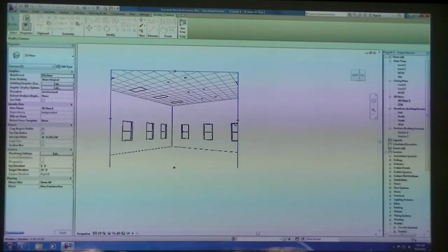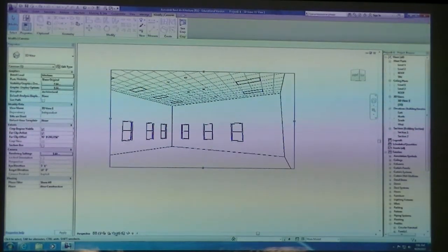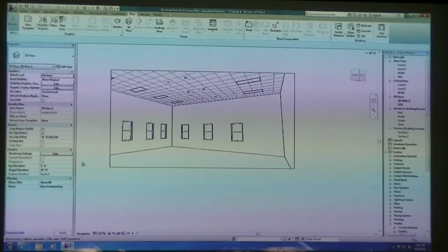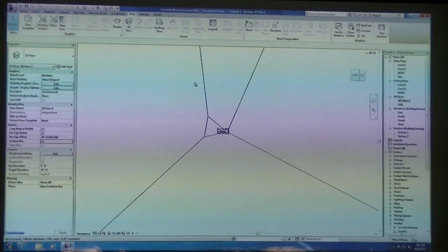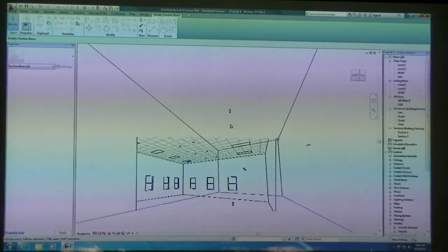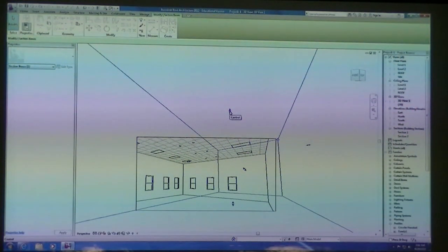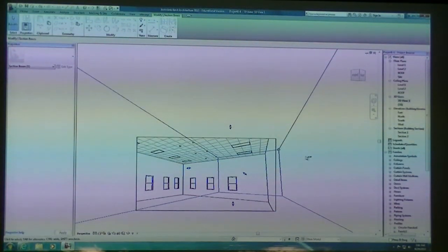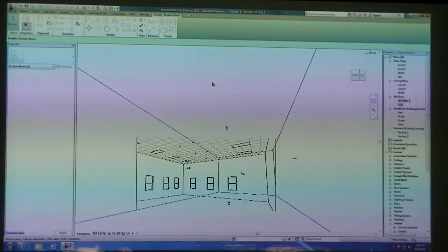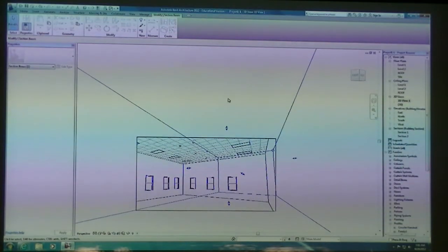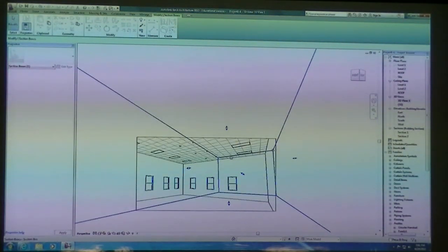It gets a little bit trickier too, but if you can show a 3D section view, you have the section box. It's not very intuitive in Revit, but remember you have this section box that cuts through your 3D model. You can drag your section box to limit how far up it goes, even though I'm outside of this crop view. You don't want the floors all the way above this to be rendering as well while you're trying to render this one particular camera shot.